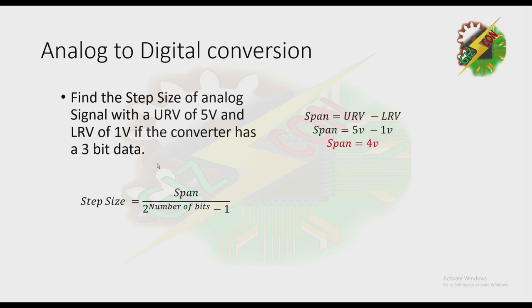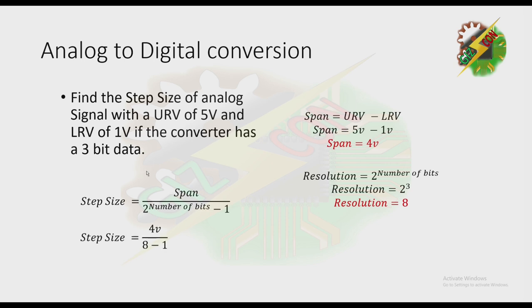First, we need to solve for the span. Then, we need to solve for the resolution. After that, we can get the step size: 0.5714 volts per resolution.